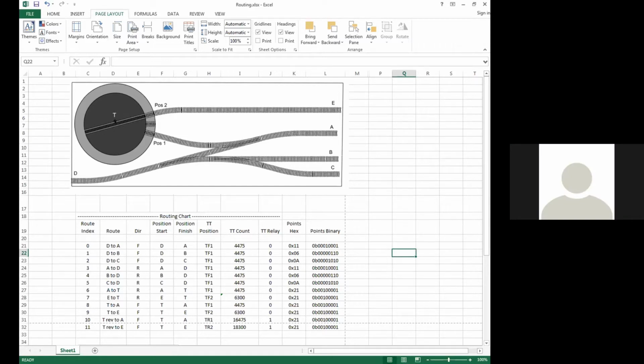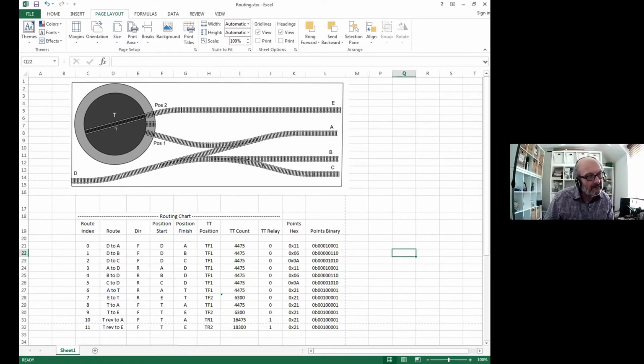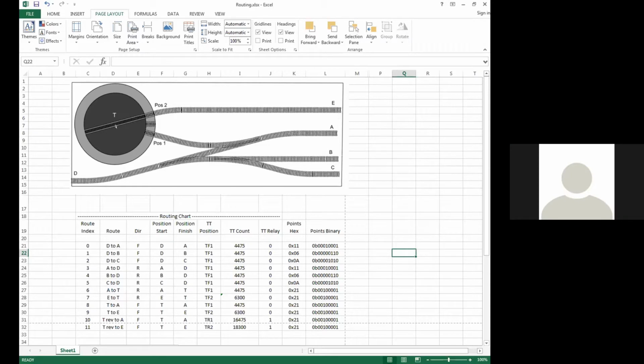What I was thinking of is a sensor that operates by emitting a high power infrared beam upwards, which hits a simple reflective patch on the bottom of the locomotive, in the centre lengthwise, and that's reflected back to an infrared sensor. So you simply have one detector, and when it detects, the loco is automatically centred.